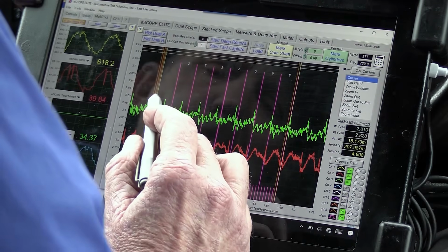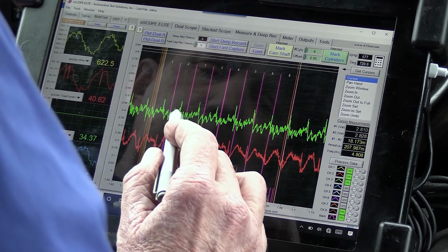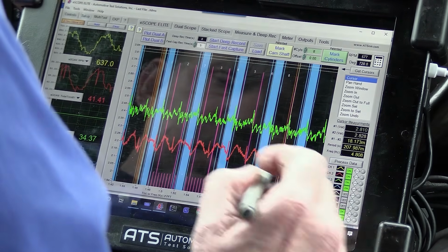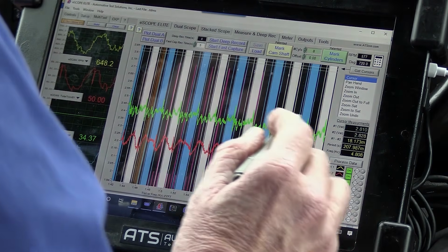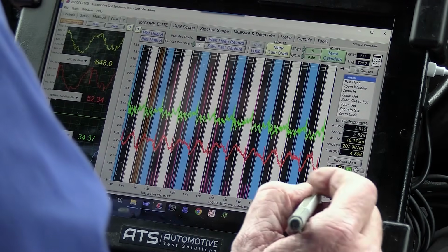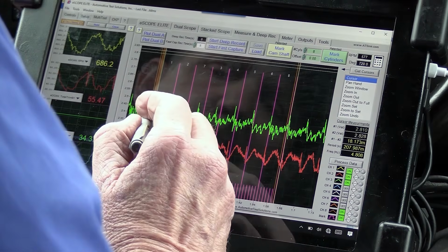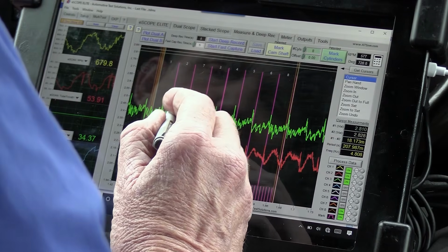Well, if I built pressure, we know the pump was turned on, because you can't build pressure unless the pump is turned on and activated. But let's just check that. Okay, for sure, it's okay. The pump is all equal. The pump drive is all equal. But the cam lobe is coming up in a different position compared to top dead center.